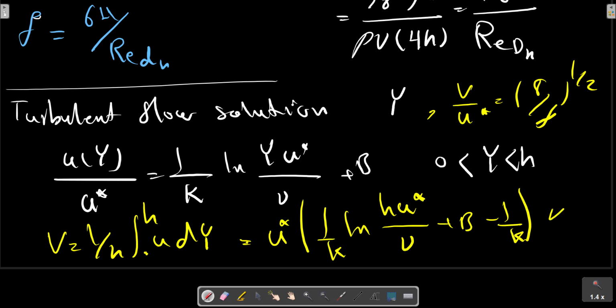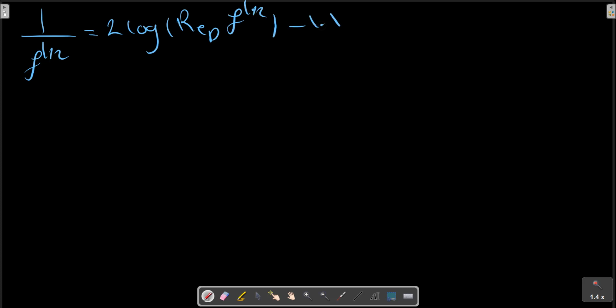We see that this equation is equivalent to a parallel plate friction law. Rearranging and cleaning up the constant term, we can obtain the relation for friction factor in this type of duct, where we have introduced the hydraulic diameter Dh, 4H. This is remarkably close to the smooth wall pipe friction law. Therefore, we conclude that the use of the hydraulic diameter in this turbulent case is quite successful. That turns out to be true for other non-circular turbulent flows also.